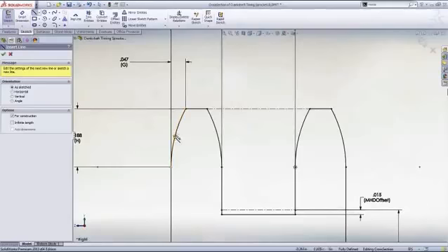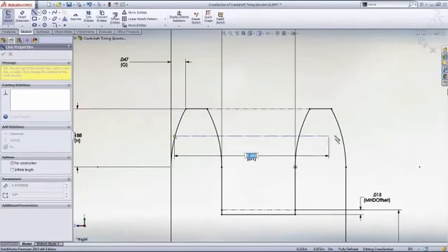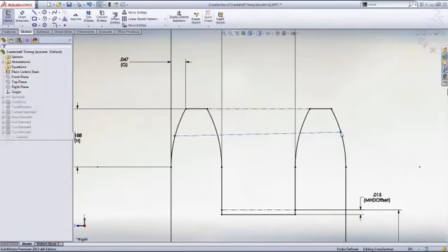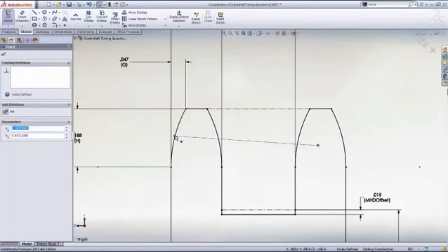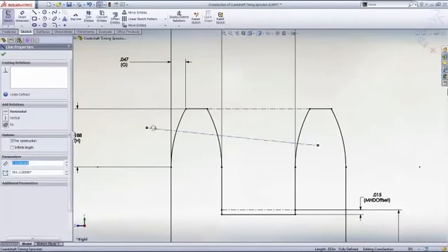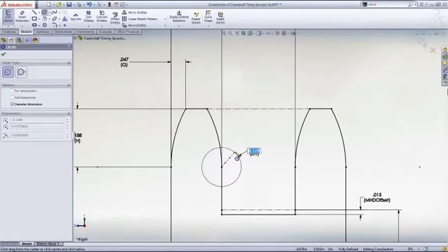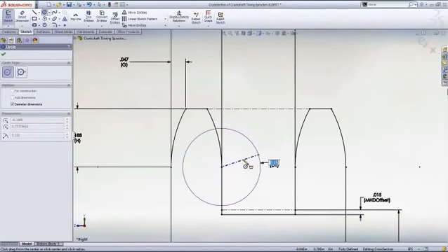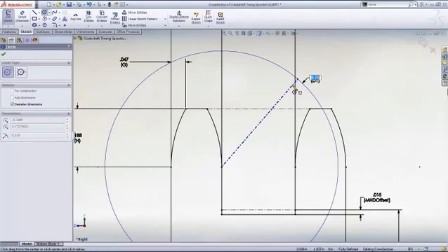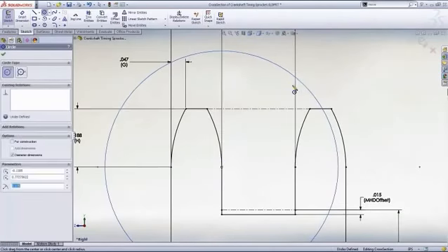Just press the Control key while sketching and you'll notice the little yellow icon next to your cursor disappears. Now, when I sketch this line, no relationships are added. I can see this when I try to move the line afterwards. Another trick while sketching is to use the grid snap increments. You'll notice while I sketch, the dimension simply changes based on my cursor position. But if I hold down the Shift key, the dimension begins snapping to 1/8 of an inch increments. This is nice if you want to draw a line or a circle to a specific size before you add any dimensions to it.